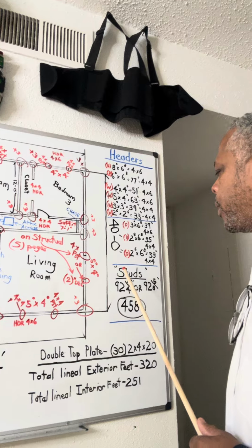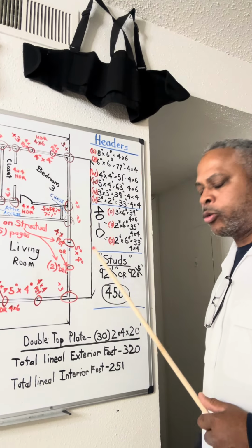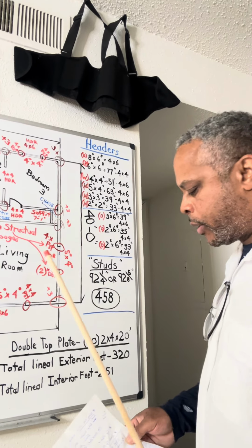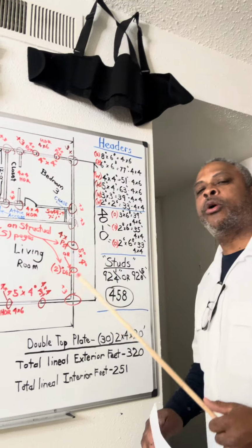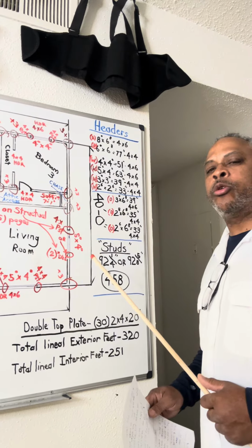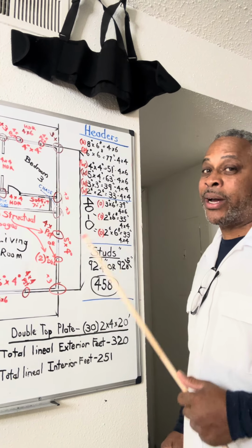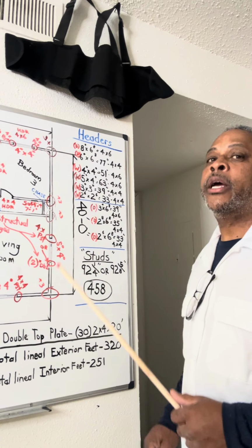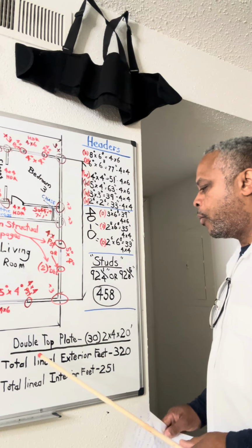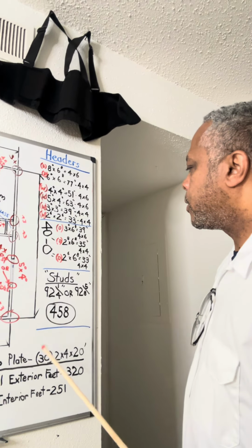So all my windows. So in the stud department, let's go to the studs. Okay, we just told you how many studs we needed. You're going to have either two sizes. On the West Coast, 92 1/4. In the South, I came across 92 5/8. Why there's a difference, don't know, don't care. Follow the plan, okay? We went over the linear footage of everything.